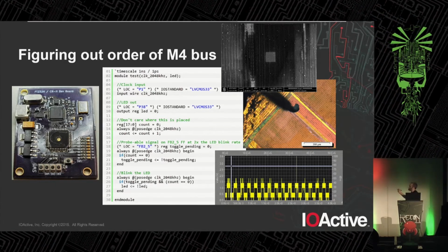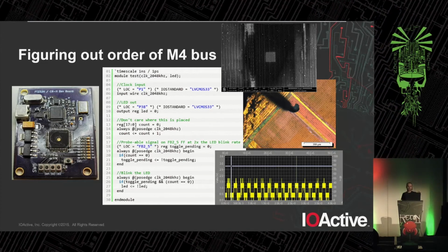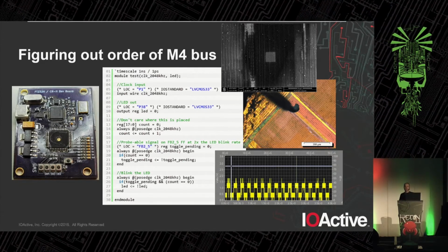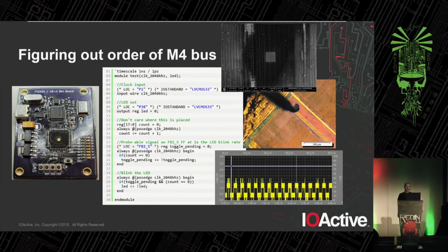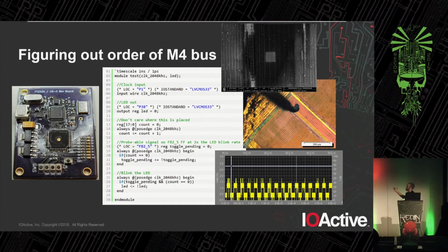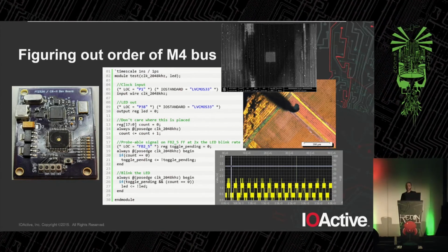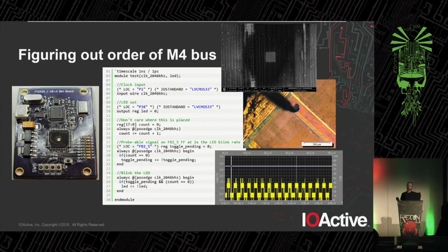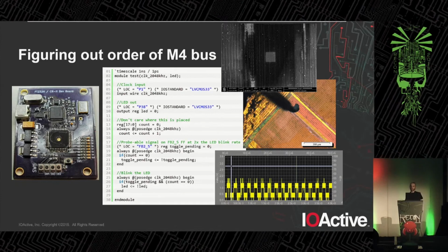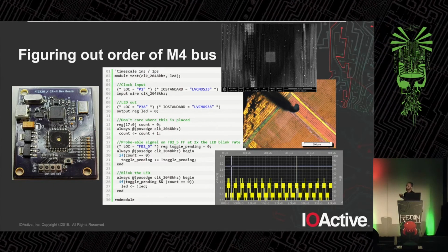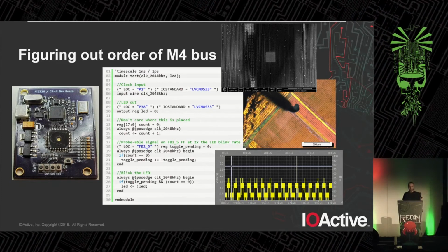Here's the code I'm using. It's just a counter going from a 2 megahertz input, dividing down to, I believe, a 2 hertz LED. And then I have one signal before that. So 4 hertz is on a specific flip-flop that I've constrained the tools. I'm like, okay, here, function block 2, macrocell 5. So let's see. If we put a signal on function block 2, macrocell 5 that's supposed to be 4 hertz, and we've got a probe pad on this signal, is it a 4 hertz square wave? Oh yeah, it is. All right, I guess it's right.